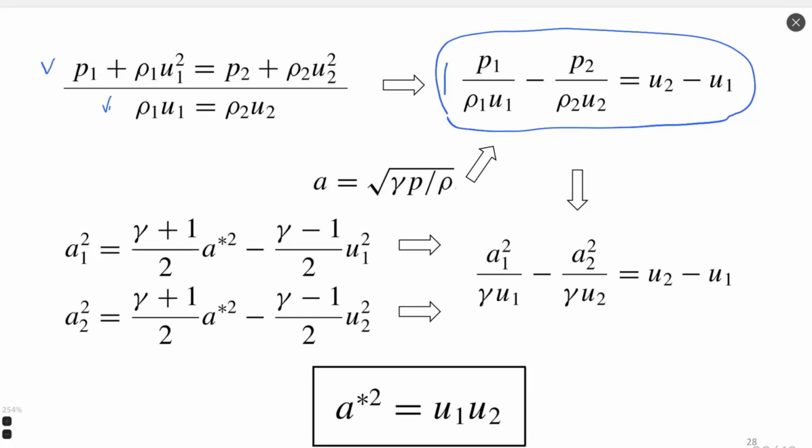And now a very important moment: we apply one of the forms of the energy equation, which you can see here. These forms of the energy equation make a relation between the speed of sound and velocity at any arbitrary point. We can choose two different points in space, before and after the shock wave.